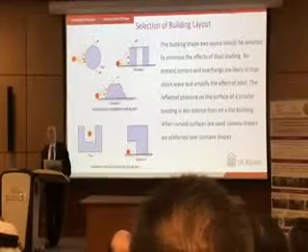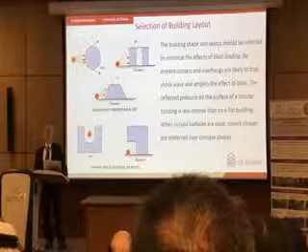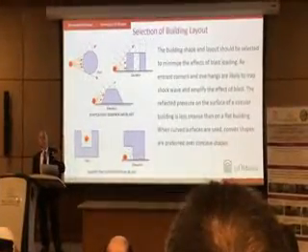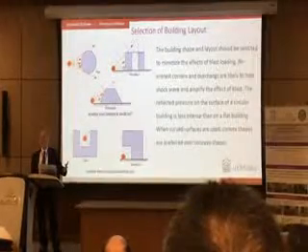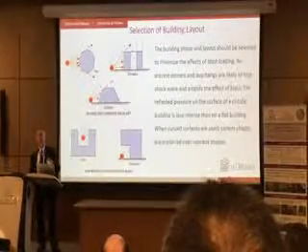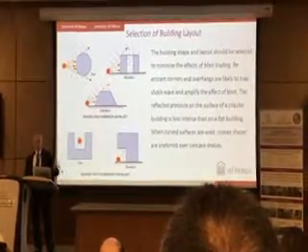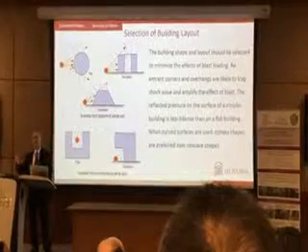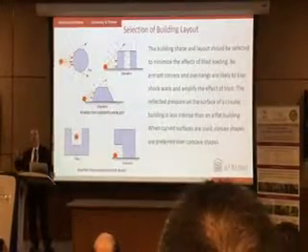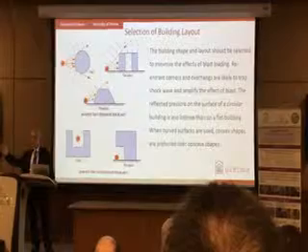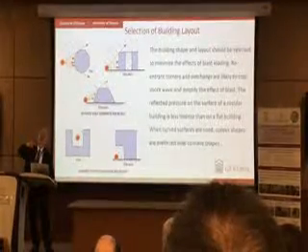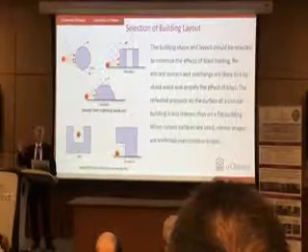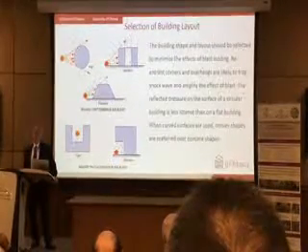Another factor I said is the shape of the building. I already talked about reflection. Reflecting of blast wave from the face of a wall is one thing, and capturing blast wave inside the building or buildings that have re-entrant corners. If the blast wave is captured in a closed environment, it hits one wall, it reflects, it amplifies. It comes back and hits the other wall, it amplifies again. So for interior blast effect, for example, underground parking is a big challenge.